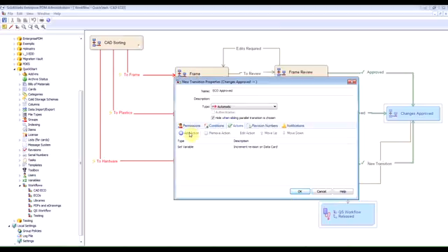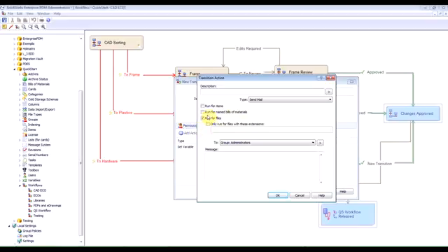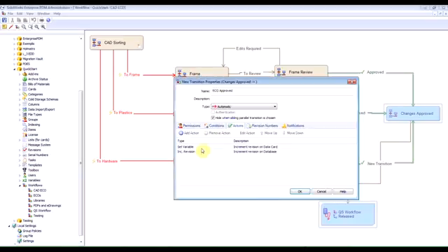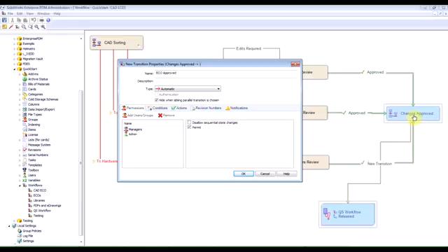That's just one part of it. We'll need to do another one. I'll type in increment revision on database. And this will be an inc revision. Stuff we're used to already to increment revision for a file. So just those two, no conditions. We want it so that whenever a file already gets approved, it just goes automatically to this new transition with incrementing its revision.